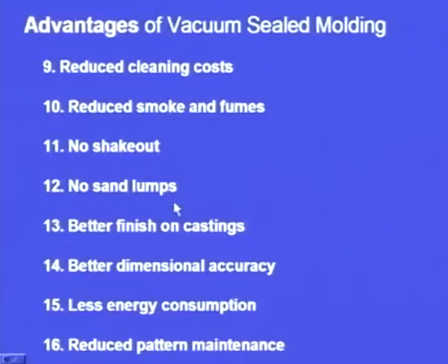Here there is no question of breaking the sand. The only thing is we have to withdraw the vacuum. Automatically the sand will fall down. The sand will collapse, clean sand. After that the casting will drop down. So no shakeout is required. That is another advantage.